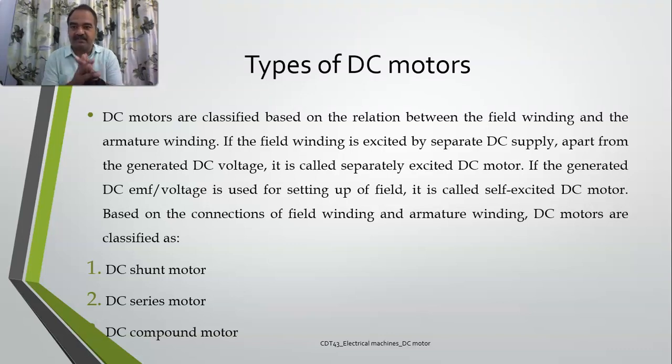So now you have seen that DC motors, how do they work? Now coming back to the construction, it is very simple. Operating principle also I told you. See, when the field winding develops a field on the stator, on the rotor you will be having conductors. When the magnetic flux is being cut by the conductor, EMF is produced. When EMF is provided a closed path, current starts flowing, so automatically there will be a secondary flux, thereby interaction of two fluxes, there will be a torque which is developed. Simple principle of DC machine.